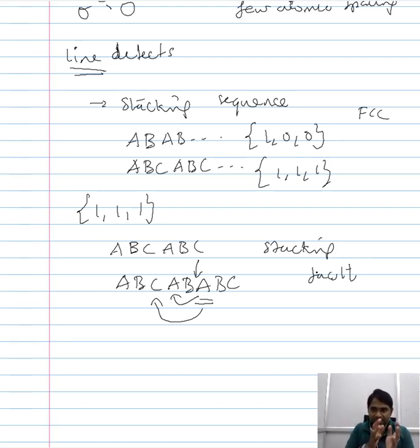Now instead of such an arrangement, you see a disturbance, meaning as we have considered here, the sixth layer of atoms, which should be equivalent to that of the third, is now equivalent to that of the fourth or the first. Then you are observing a defect in the arrangement of the atoms, and this defect is not confined to a point, but it extends over a line, and this we refer to as the stacking fault.